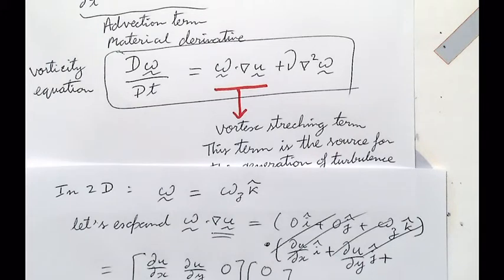So in the field, the word turbulence is used very specifically. You have to have a minus 5/3 slope of the energy spectrum. If you're talking to a very established researcher in this field, they will always ask, "Hey, is it fully developed turbulence?"